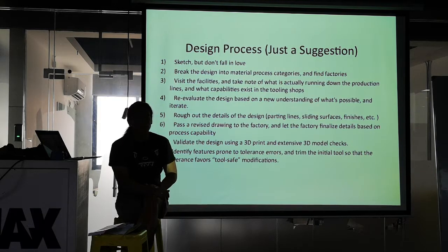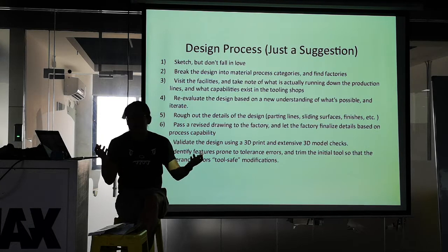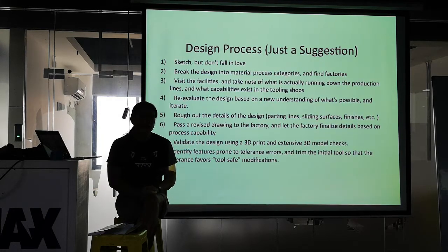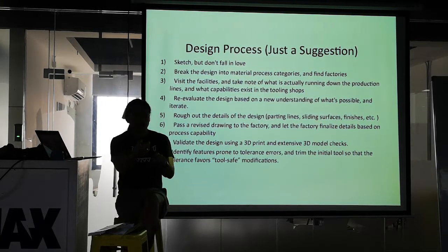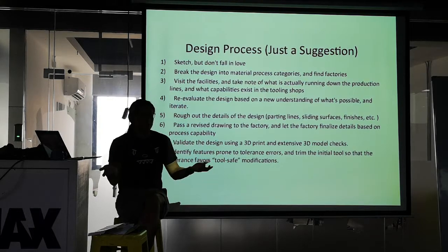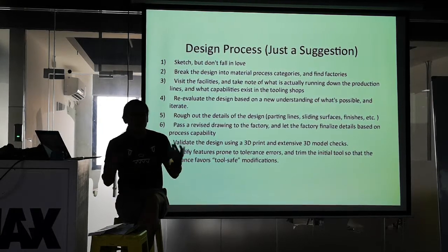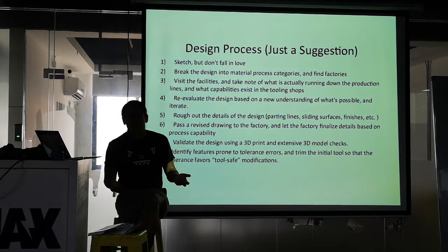Or for example, if you're doing electronics and you're not sure, you have some analog filter, right? You're not sure what topology it's going to be. Guess what? 2 shunts and a through is either 2 components that aren't there and a 0 ohm resistor, right? So you just put that on your board. Later on, if you need that filter, you don't even know what the topology is. RC, RLC, whatever it is. Guess what? 2 0402 pads plus a shunt 0402 pad gives you all the topologies you can get. You never have to remanufacture that circuit board. It's just a BOM change later on down the line.